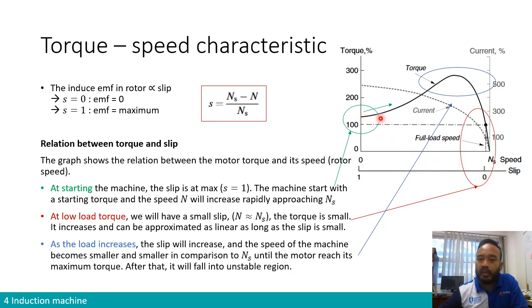So what's going to happen? The torque will also move in this particular form until it tries to reach the point of synchronous speed. But if your machine has a certain load, it will not be able to go all the way to synchronous speed. It will stop at a certain place, the operating point, where the torque is equal to the load resistive torque.